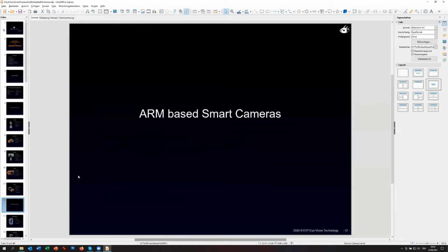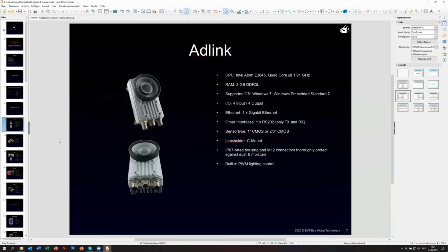And furthermore, which one is a better or the not so good camera? It's difficult at the end. One has to decide what do I need, for example, how much computational power, what is the right solution which I need? Does the manufacturer have the solution for this smart camera? This is a major difference to a standard system. You buy the smart camera as a fixed combination of sensor and computational power.